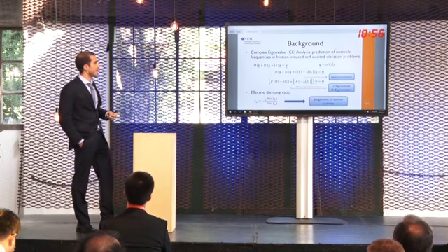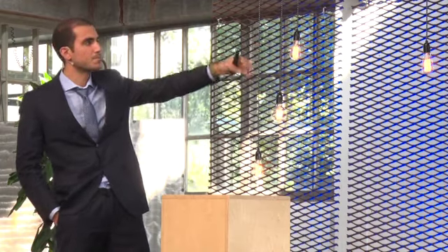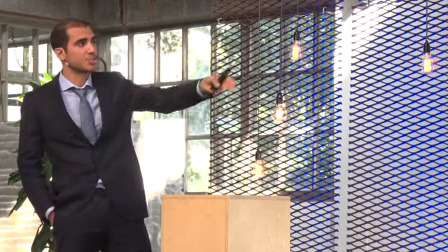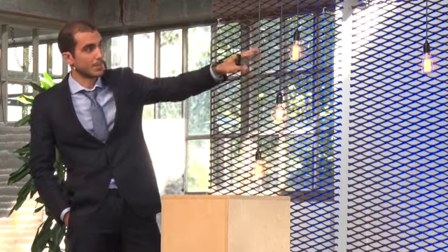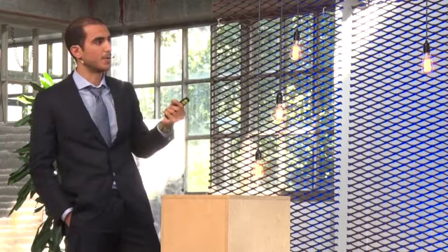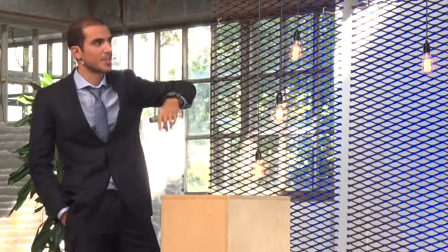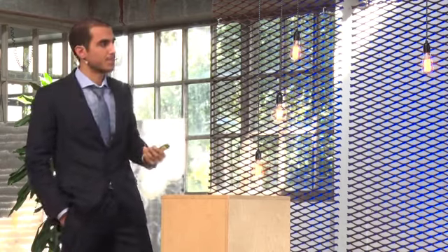Here we can see very quickly the logical flow of the analysis, which is called complex eigenvalue analysis. We start from the structural linearized equations of motion of the system, where Q is a vector of the external forces, which in this case is just related to the friction forces of the system. If we look at the global stiffness of the system, we can see that the matrix is not symmetric, and therefore it can lead to flutter instabilities.